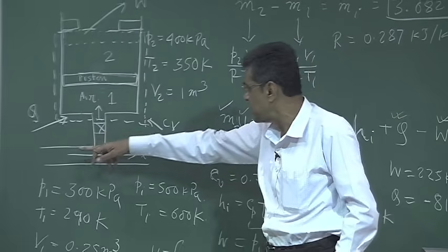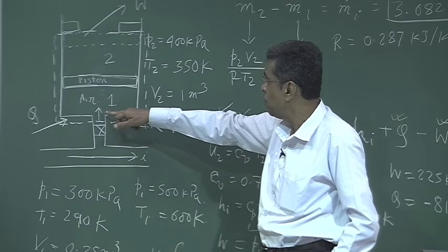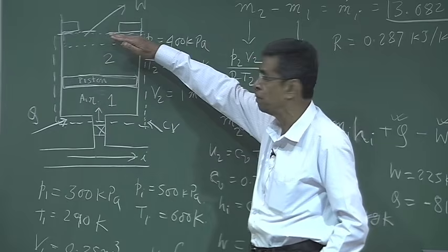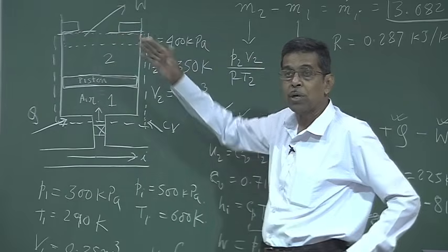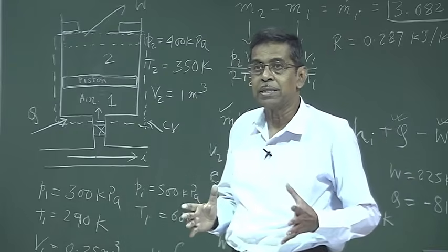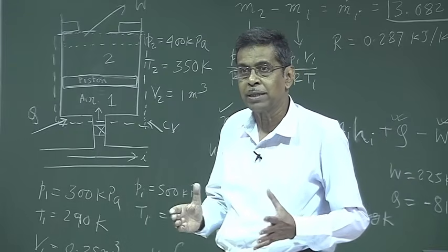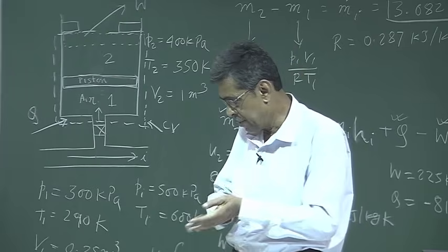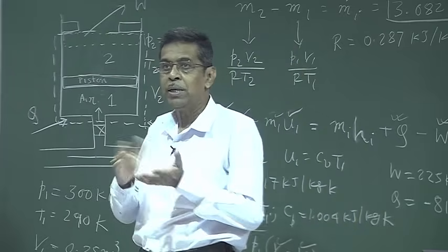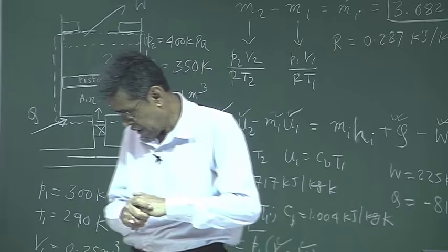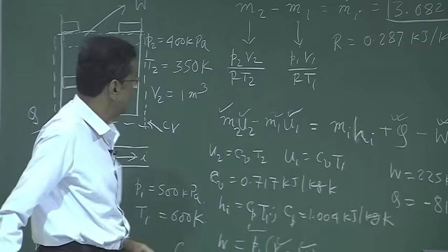This is an open system where there is an inflow, but it is an unsteady open system, there is no outflow, but the air pushes the piston to go up. So we can have PdV work even in an open system, but this work requires a quasi-static or a reversible process, which we will discuss afterward. A very slow process, so that there will always be thermodynamic equilibrium of the system. Okay, then this is the problem.